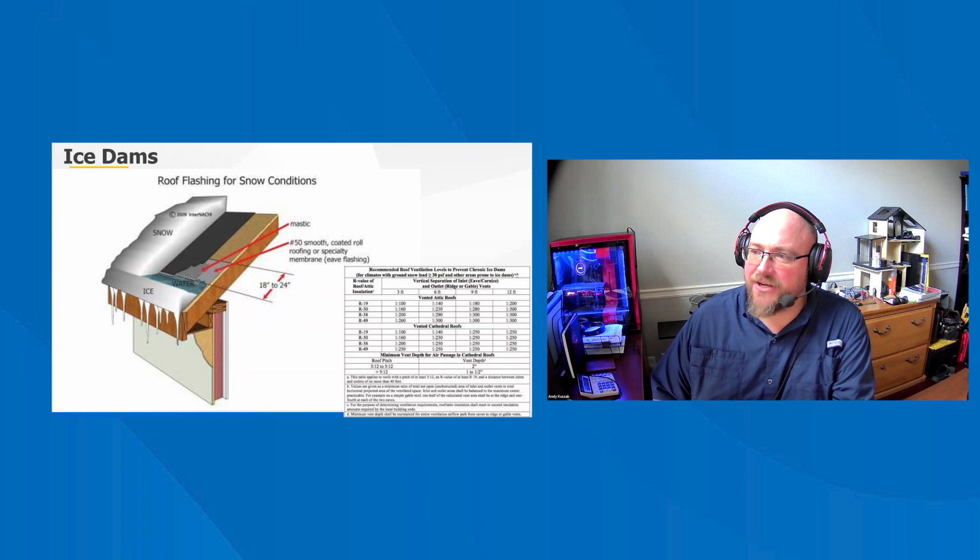Air leakage from the interior into the attic also introduces moisture. If a significant amount of interior air leaks into the attic, the ventilation in the attic may not be sufficient to prevent moisture and condensation problems. For enhanced protection against formation of ice dams, the table provides recommended insulation levels and vent area ratios as a function of the venting layout.